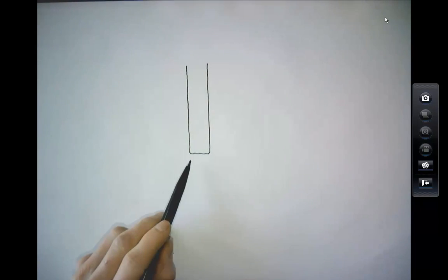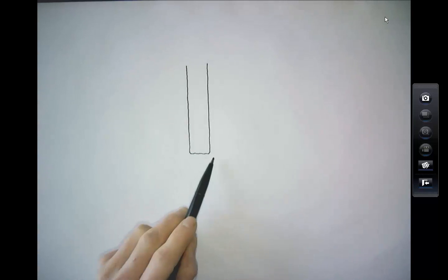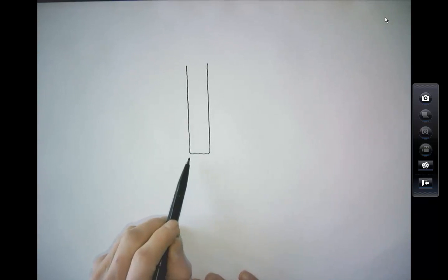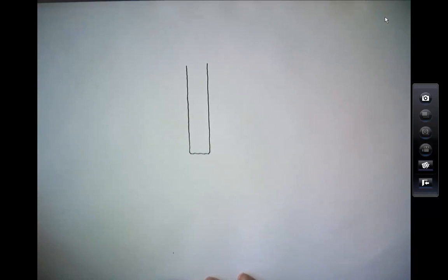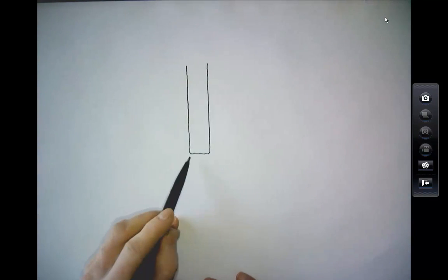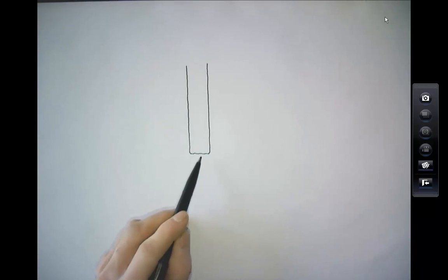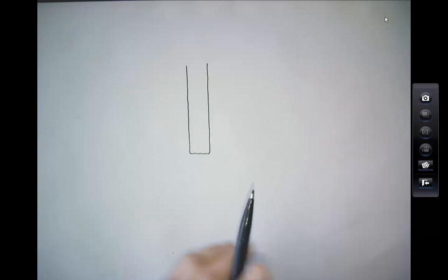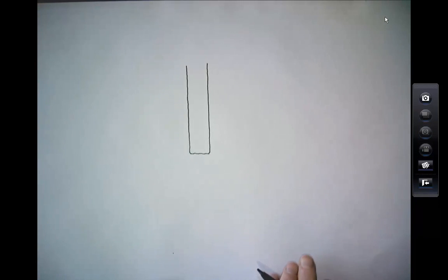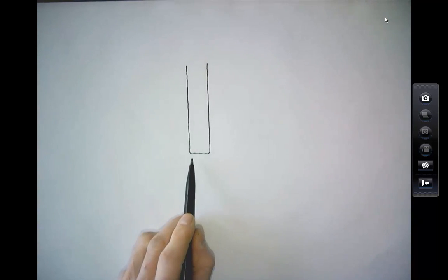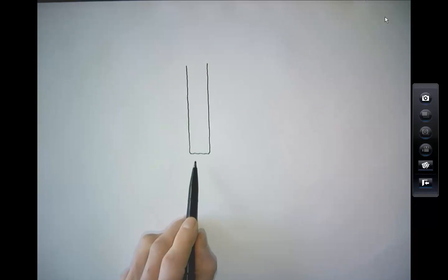And I'm drawing the corners that have been chamfered off on this detail. I'm using the detail again. So they've chamfered the corners off. You don't have to, but it probably makes a better detail. And if you look at the sample here, if you don't chamfer the corners off, you could end up with kind of irregular parts. You could end up with sharp bits. So quite a good idea here just to 45-degree chamfer off the CLT.